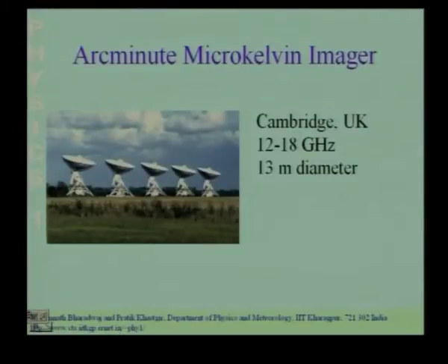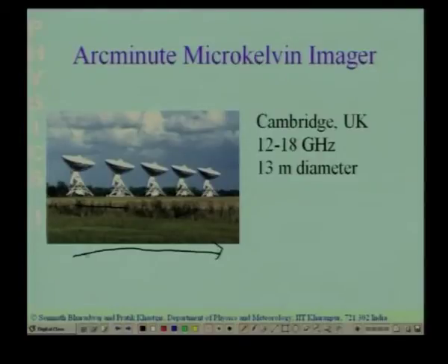What is going to happen is that one of these antennas, so each of these antennas we have seen, if I had only one antenna, it would emit or receive radiation with a resolution of 0.12 degrees. But now when I use this as an array, its resolution is going to be decided by this total length over here, and the resolution is now going to be of the order of lambda by L instead of lambda by d, and this number is going to be smaller.